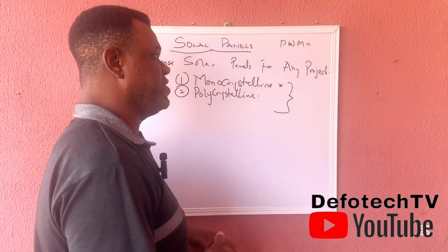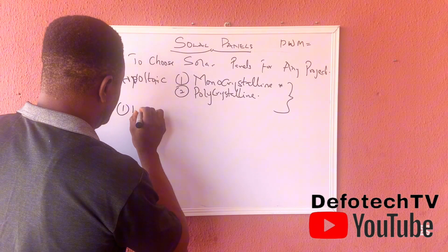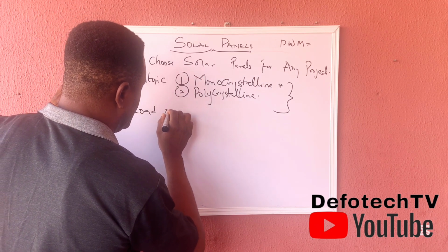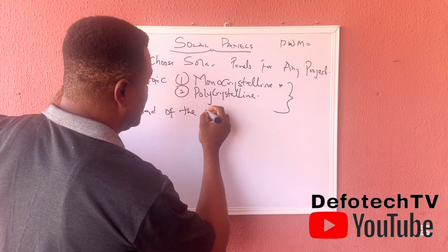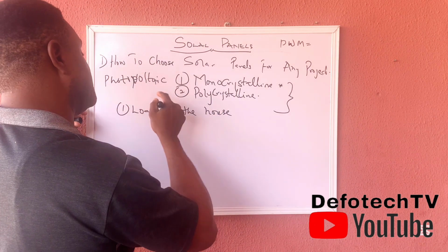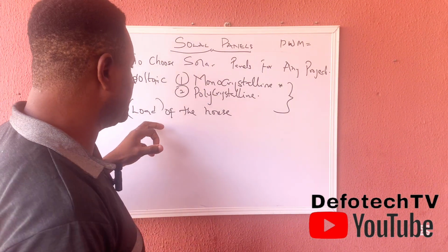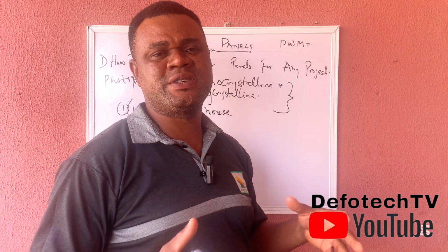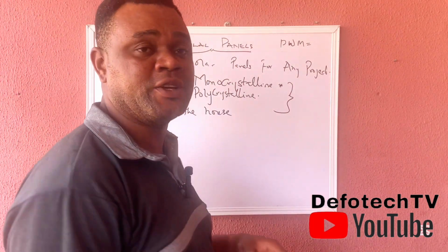It is very efficient. Now, you have an installation, and you're thinking, okay, what do I need to calculate for? Number one, you need to calculate the load of the house. If I say calculate the load, you need to know the size of the equipment you have in that establishment that your solar panels will be powering.